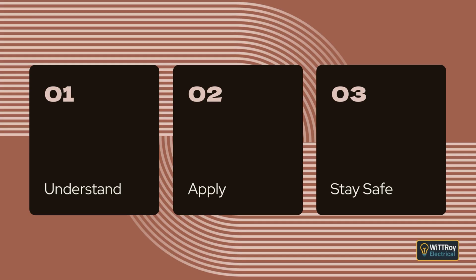This is only allowed when, first, opening the circuit unexpectedly could create a more dangerous situation than the overload itself. This applies to some safety systems and specialized industrial equipment. Second, the conductor must not be in a location where fire risk or explosion risk is high.